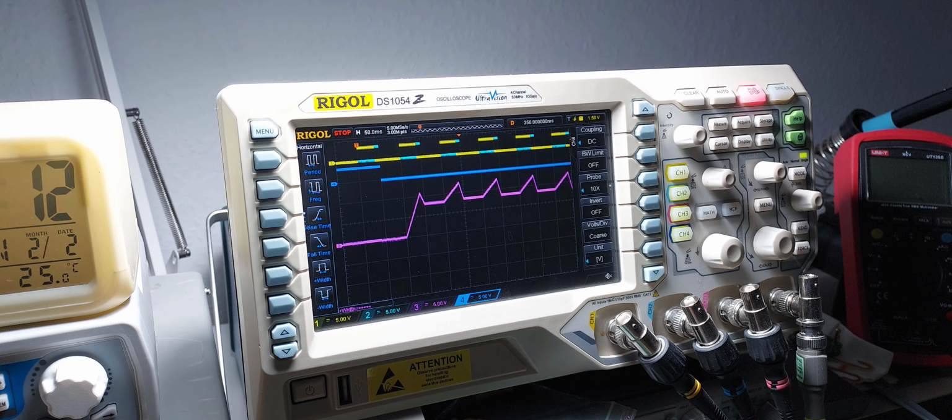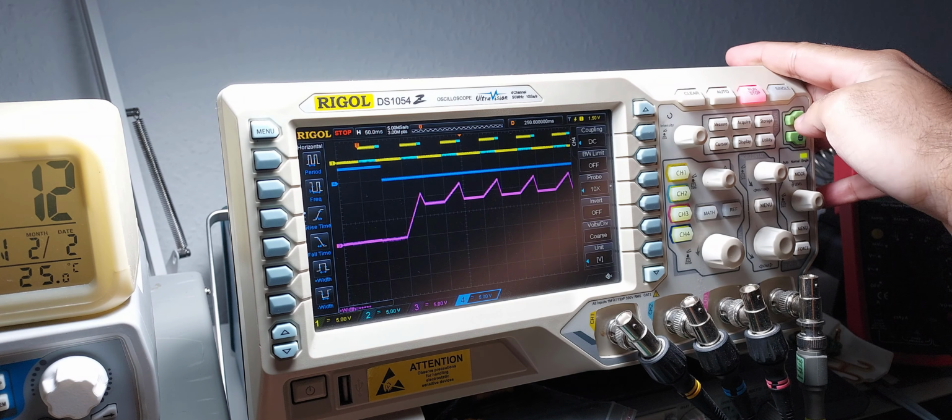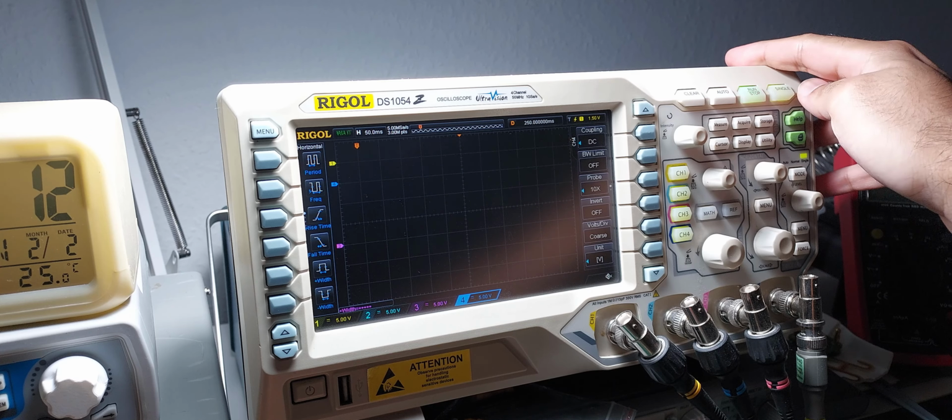During the first PWM cycle, the integrator ramps up from the 0 volt reset state to a value proportional to the duty cycle, an up period and a down period, after which the PWM signals are blanked, that is, neither reference is switched, preserving the DC value of the previous period.